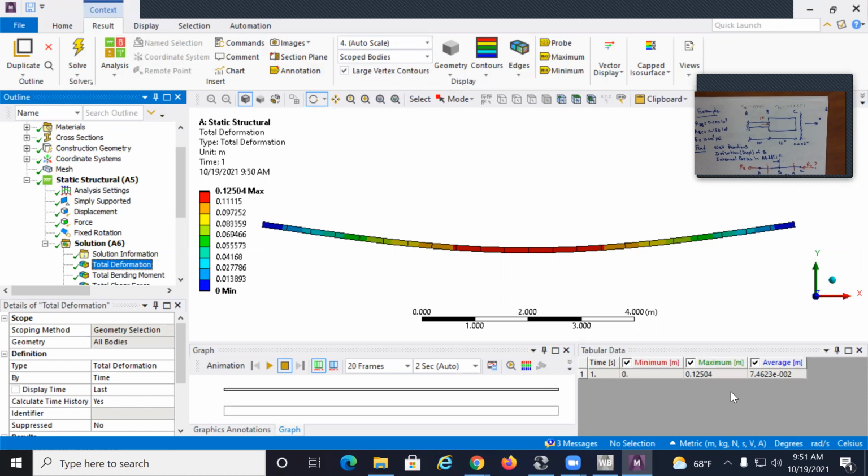There is also an axial stress due to a normal force that, according to the terminology we are using in ANSYS, would be called direct stress, or I can call it also axial or normal stress. This is also a sigma x, but will be equal to the normal force divided by the area. Is that concept clear?